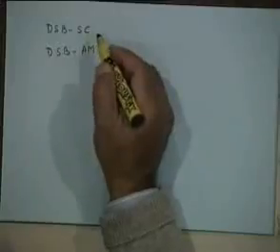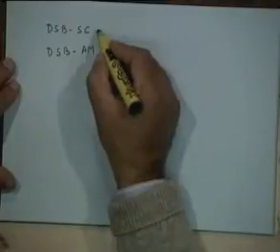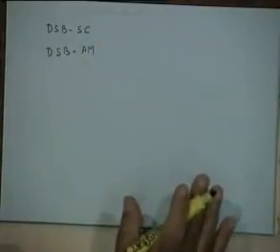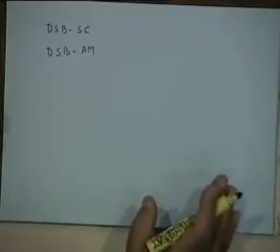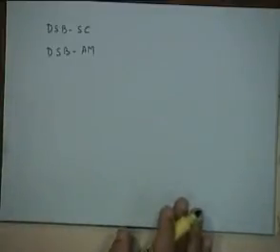What are the pros and cons of these? Bandwidth efficiency is the same for both of them, right? Both of them would require twice the message bandwidth as the final transmitted bandwidth, right? So there is no difference in the bandwidth efficiency of the two waveforms. However, in terms of power efficiency, which one is better? DSBSC is much better, right?